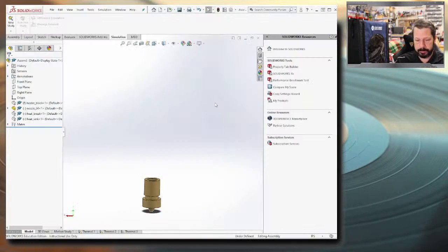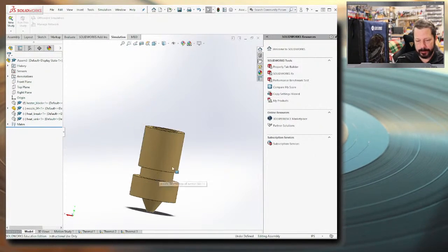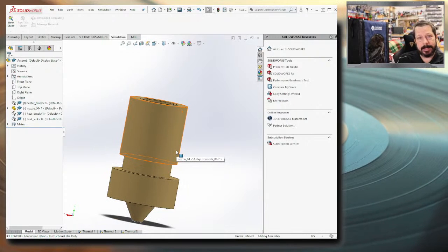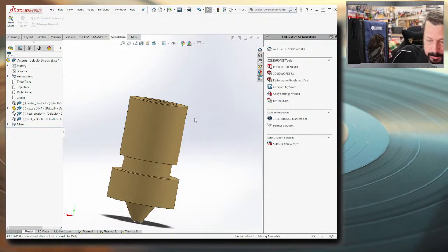Here's the model. Only the nozzle is visible right now, so I'm using the nozzle. I'm not modeling threads. You can see I've made every part that's a thread just a cylinder to represent the contact. I'm not particularly interested in the actual thread-to-thread interface. We can even model that without the geometry, with coefficients in SolidWorks, if we really wanted to.